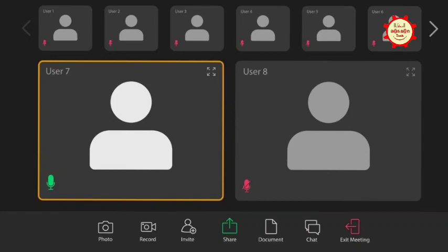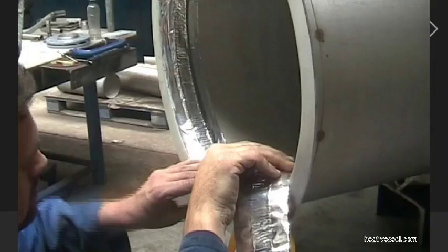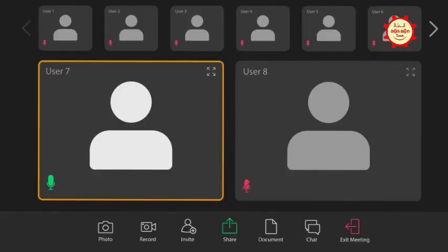In the bundle there is an option: I will provide a sliding strip, and the floating tubesheet is in the air all the time. You provide the sliding strip on the tube bundle. We insert the backing ring and floating head into the tube bundle, and we assemble the bonnet shell to the main shell. Then we insert the tube bundle in the main shell. With the help of the sliding strip, it will slide smoothly into the main shell.